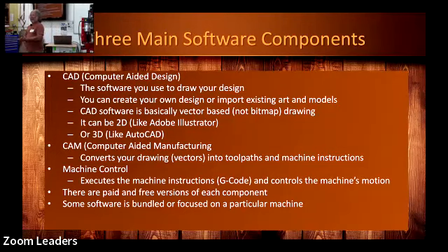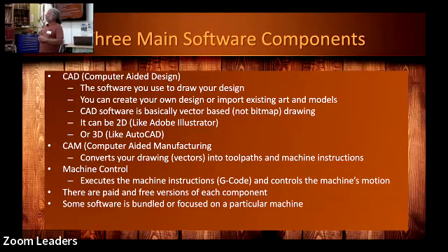Well, that's great, but now you've got to make it. So now we need something that's going to convert that design, those plans, into instructions that can move that bit around and have it make what it is that you want it to make. That software is called the CAM software, computer-aided manufacturing. That software's job is to do just what I described. It basically takes your drawing, could be 2-dimensional, could be 3-dimensional, and turns it into cutting instructions for your machine. Critical piece. The output of that is a script, a program. The program basically says, take the head and move it down here and move it over here and turn the thing on and cut it over here and go back and forth a few times like that and then drill a hole and you're done. That's kind of the program, the script, if you will.